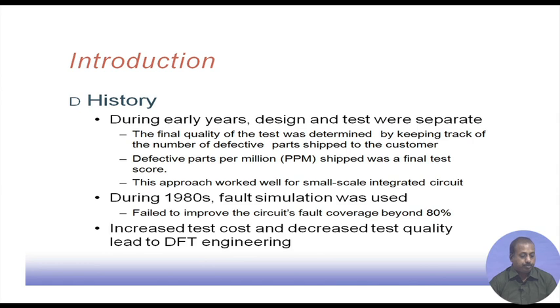That way we get some idea about the quality of the test vectors that are applied, and we try to modify the test vectors so that this coverage improves, but getting coverage more than 80% was difficult. In our introductory classes we have seen that even with 90% fault coverage, there is a huge loss in the number of defective parts that are sent.